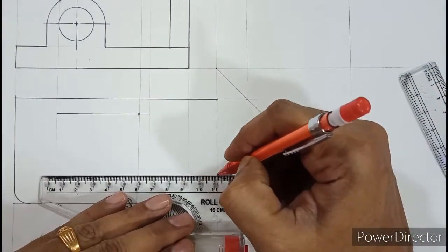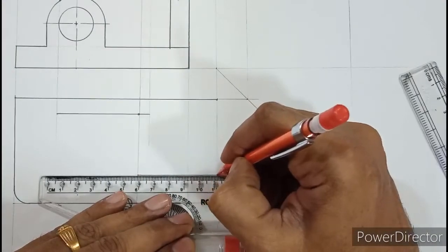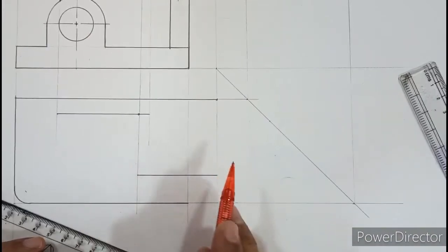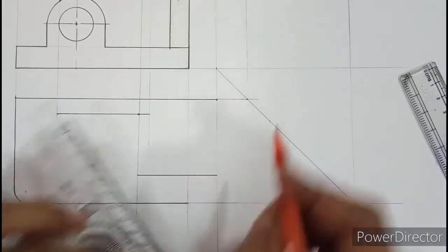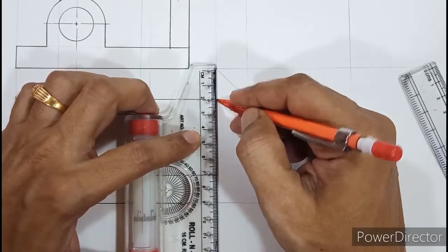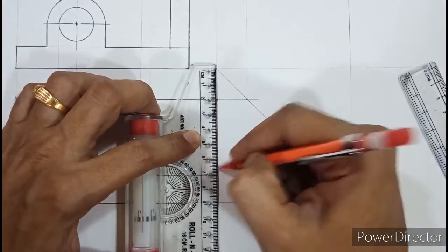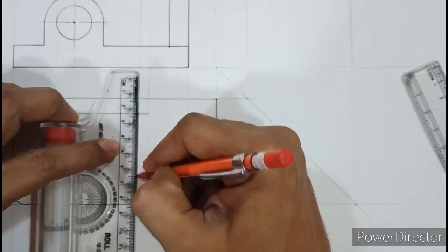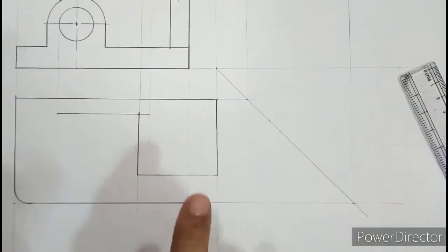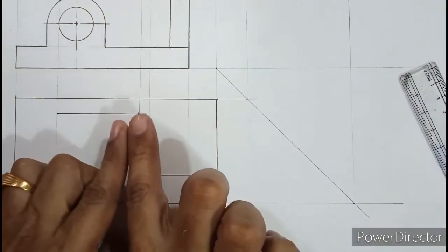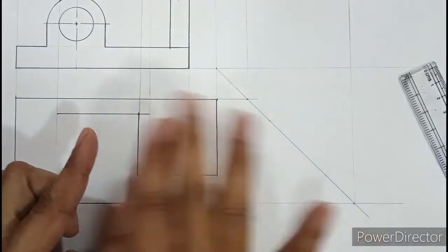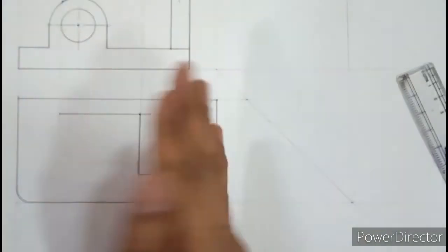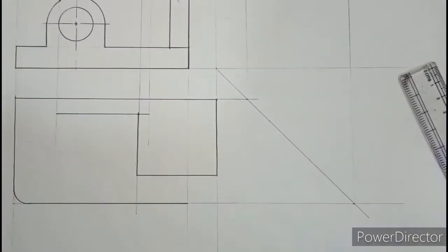So now this horizontal line, what I'm going to draw, see this line, what I just drew, actually in the top view it's a circular edge. So you have to visualize this to be a circular edge, which is seen as a straight line. Now this boundary is the right side boundary of the cylinder, what you can see, and this is the left side boundary. Both are unequal by 10 millimeter. So if you look from far enough, don't visualize this as a flat surface. For some time assume that this is a curved part, like this. It's a curved surface which is seen as a flat surface. So that imagination is required.